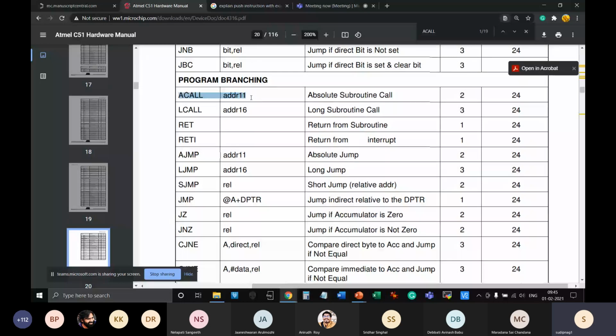Okay. So the modified call instructions are available in ACALL and LCALL format. LCALL is basically similar to the simple call instruction. Long call means you can again address an entire 16-bit location. It is actually the same as simple call, so both mnemonics can be interchanged over here. But ACALL is slightly different. ACALL only has 11 bits of addressing space available. So that means you can only go within a 2 kilobyte space, that means 1 kilobyte before and 1 kilobyte after.